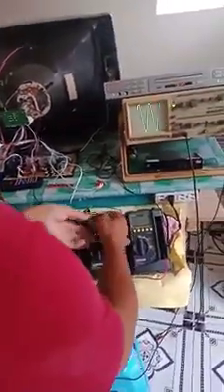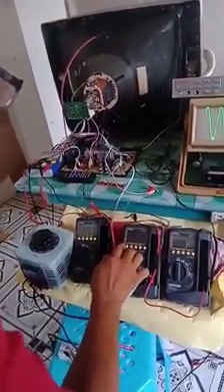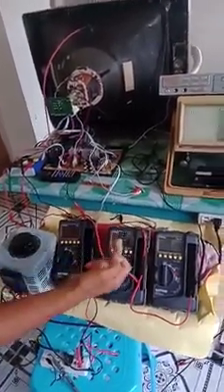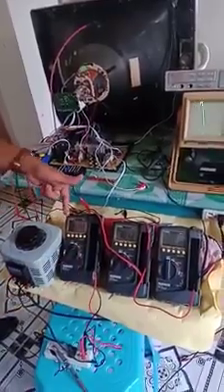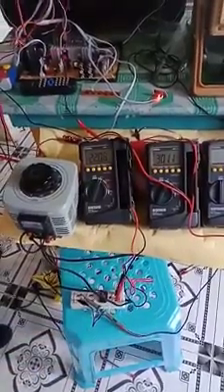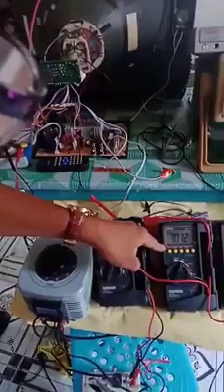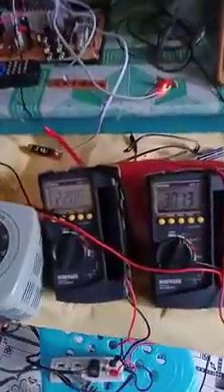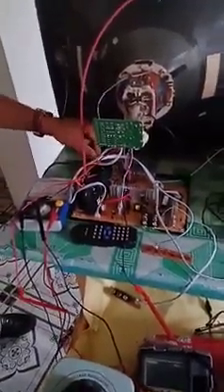So, what will be the voltage across this? This digital meter is set to AC voltmeter. It now registers the 220 volts, which measures the voltage at the outlet, the actual voltage distributed to the TV receiver. This second voltmeter is set to DC, at the output of the rectifier diodes or across the supply filter capacitor.